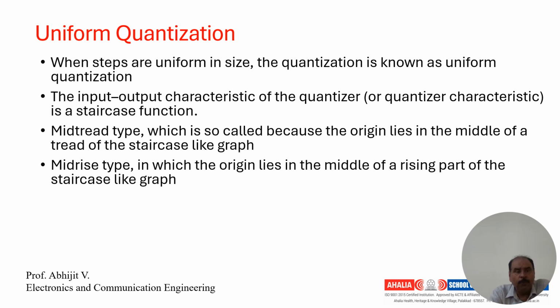So what is R? R is the number of bits per symbol, right? This shows that the output signal to noise ratio of a uniform quantizer, SNR_Q, increases exponentially with the increasing number of bits per sample R.